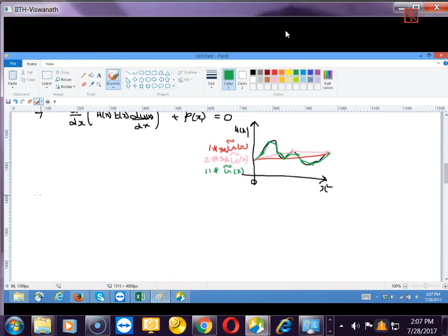These are h convergence, and what we said was, when you are picking the basis of an interpolation function, the shape functions of the element, to develop a shape function, which is like u tilde of x equals capital X times a naught, a1, the best choice would be 1, x.